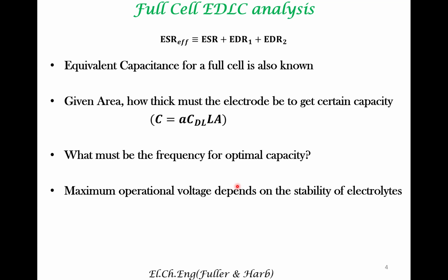If you want a broader, greater voltage window, you typically operate using organic electrolytes. They have their own challenges, in the sense that the ionic conductivity of an aqueous electrolyte is typically more than the ionic conductivity of a non-aqueous organic electrolyte.